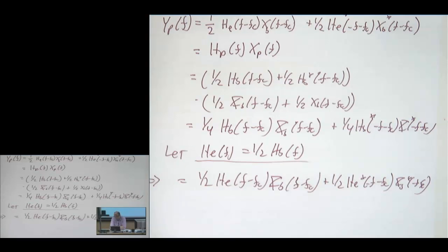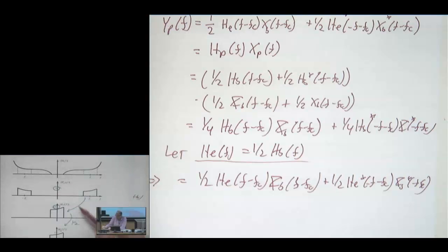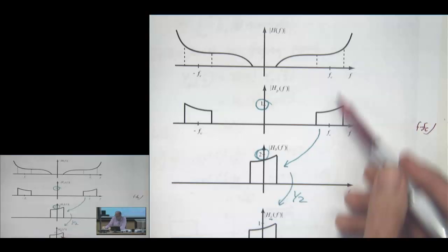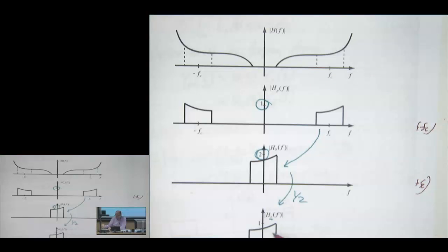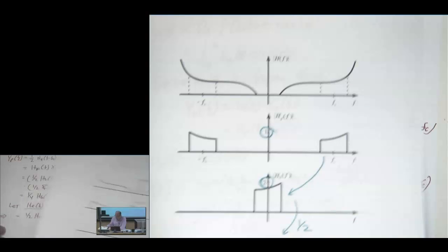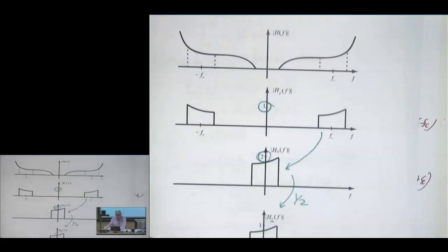And so having this mathematical model, this piece right here, is essentially going through this whole exercise. A modem, of course, doesn't do this. This is really just connecting propagation theory and channel modeling to DSP. So that's the main reason we do this here. And once we know this, we know there's a band-limited impulse response that characterizes the channel between the input and the output of my passband signal. So then all I need to do is learn this. And because it's band-limited, we can sample it and do everything in discrete time. So that was the end of this piece of the lecture.